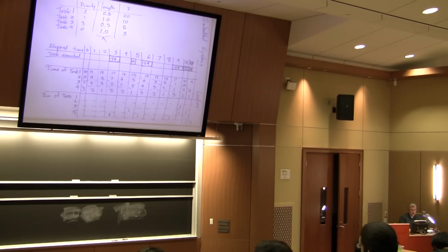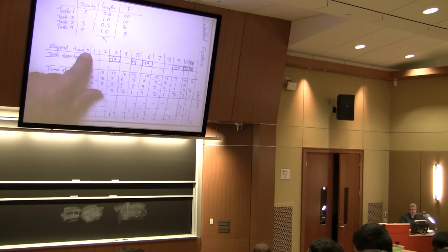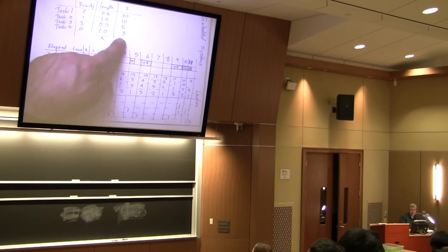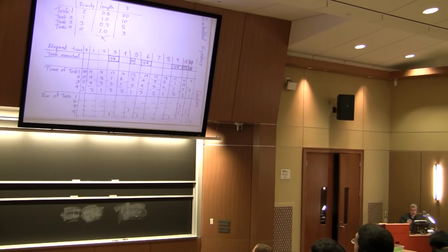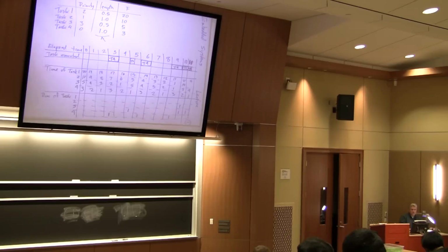So if your microprocessor is running at 50 megahertz, and this timer tick is 1 millisecond, if your microprocessor now runs at 100 megahertz, this timer tick would still be set at 1 millisecond, because it's the task that has to be done at a certain frequency. And the frequency is based on real time, the time of the world, not the time of the processor. So as you can imagine, if you had a microcontroller that's running at 25 megahertz, that would be really bad. But if you could run it at 100 megahertz or even 200 megahertz, then you could get a whole lot more, or you could ensure that you don't have a lot of tasks that would conflict with each other.